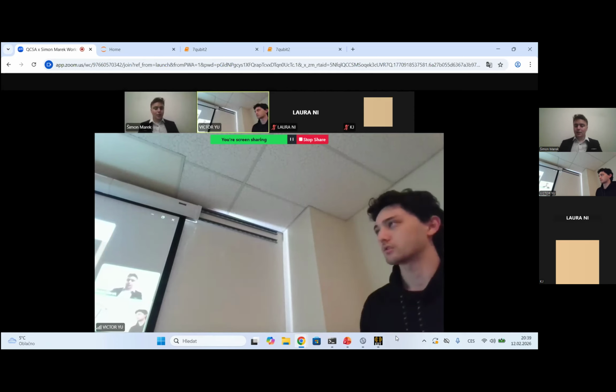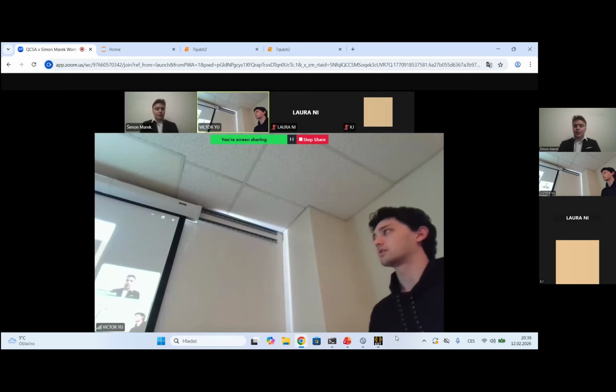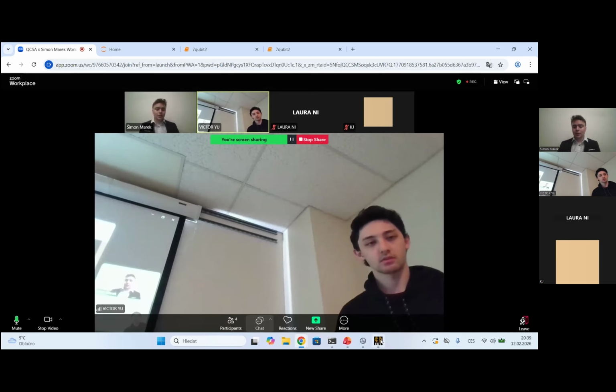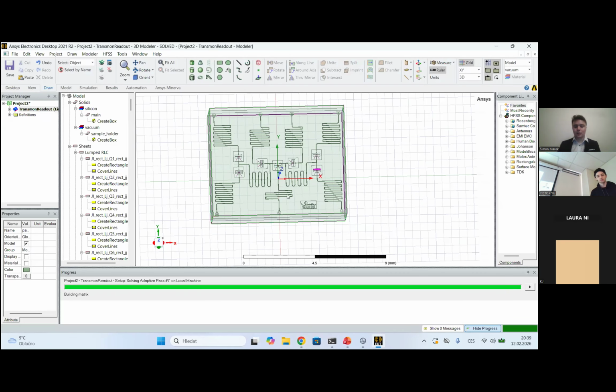Yeah, sure. So very simply, we design our layout simulation, we don't need anything, just a Python file, and from this we can export it to ANSYS, and we can verify the post-layout simulation by running EPR. It is very convenient because we don't want to fabricate our quantum chip without knowing its parameters, because we at least want to verify the parameters for meanders.